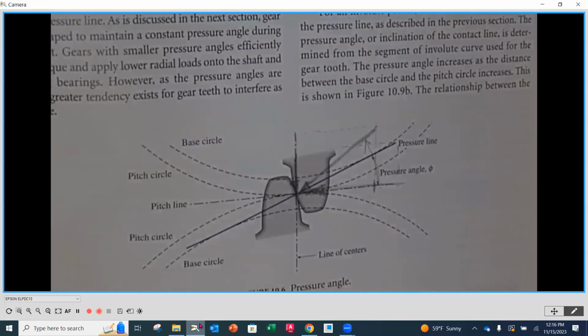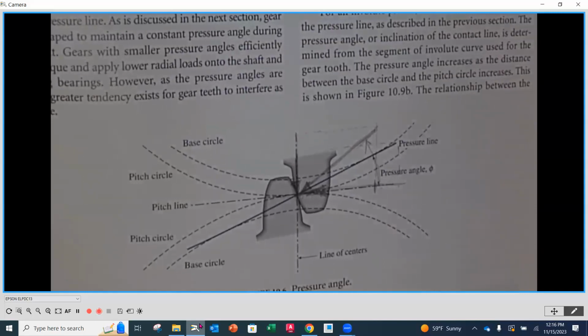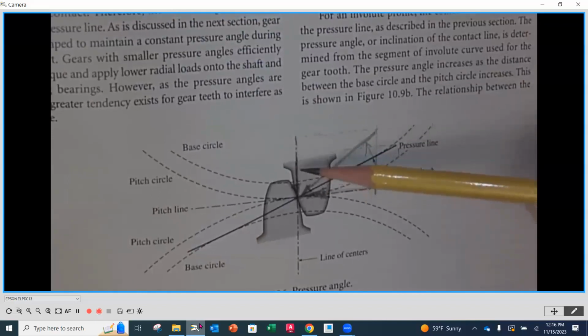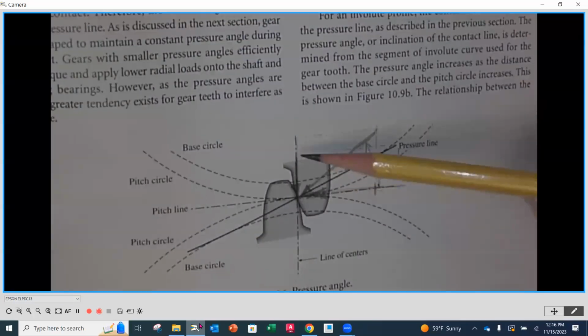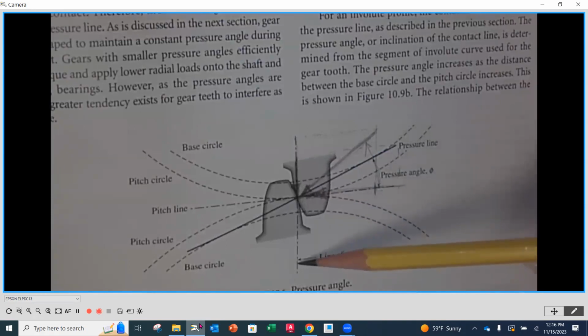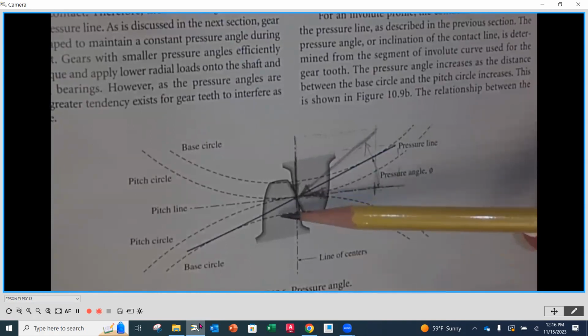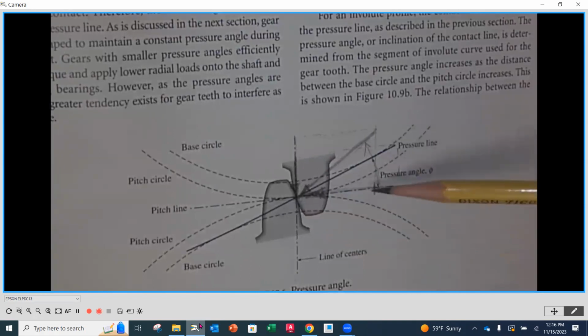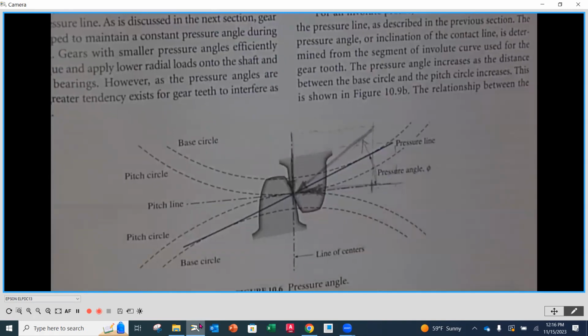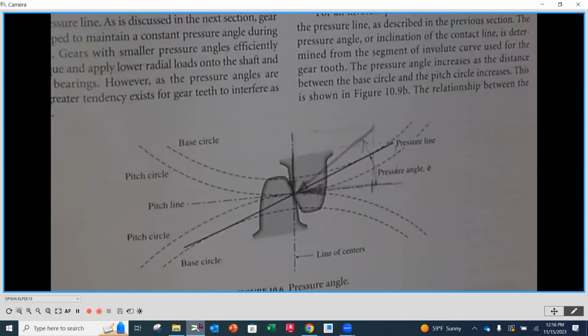More what? Say a different one, not mass. What am I pushing down through the center where the actual material is? It's not mass. It's a force. I'm going to be pushing this force down through the center of the material instead of shearing off a tooth. So if I can minimize that tangential force, there's less force wanting to push that tooth over or shear it off.